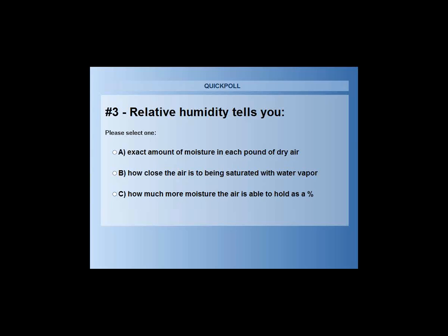Residentially, a lot of systems we ship at Carrier are already defaulted to 300 CFM per ton. Over the years, we've dropped that number down. If you're in some really dry climate like New Mexico or Arizona, you need a lot of airflow. But in more temperate and more humid climates, I want the blower speed to be lower so I get more latent transfer. If I slow the blower down, I get more latent capacity versus sensible capacity. So a good target is about 300 CFM per ton if the equipment you have is designed for that.